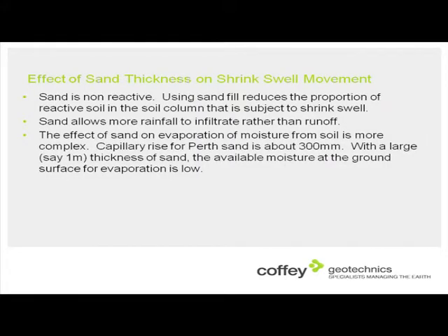How does the sand influence what we do? Well, the sand's non-reactive, so it doesn't shrink and swell. So that portion of the soil column within that depth of soil suction change is reduced. The top bit, which would have the greatest moisture changes, is non-reactive now if we put sand over it. Another effect, which there's no provision in the Australian standard to allow for, is that sand will allow more rainfall to infiltrate. So effectively, we will be emulating a wetter climate. Sand can also have an effect on the evaporation from the soil.